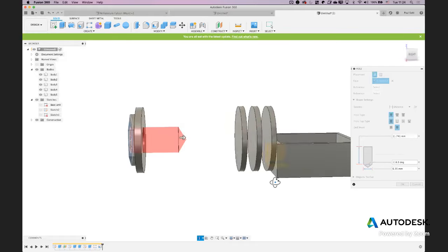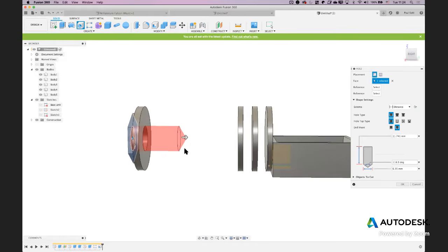Once it's snapped in place, you'll also notice that it has a point on it. This is because it's simulating a drill bit. Of course, you can change that, but for the sake of today's exercise, that doesn't matter. The other thing I want to highlight to you is that you can also add a counterbore or a countersink as part of that same operation in case you need those voids for the kind of screws you might be using. In our case, again, doesn't really matter, but would like to let you know it exists.